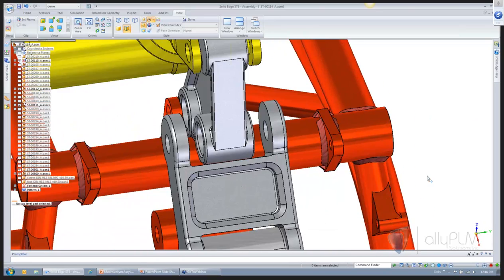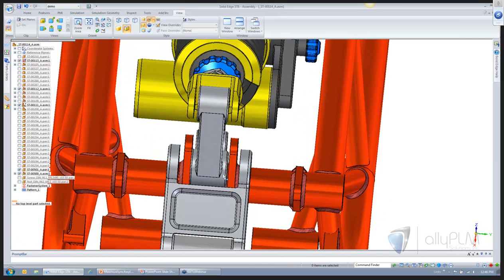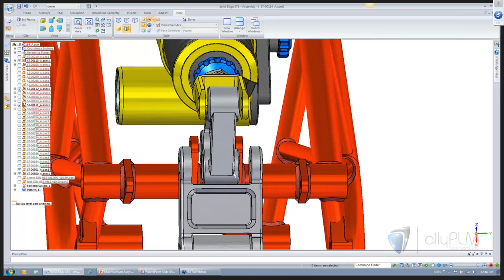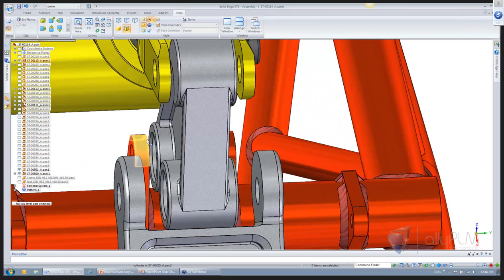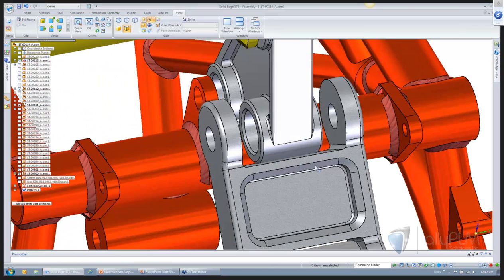Positioning the steering wheel is key to all synchronous edits, both of the part and the assembly. What we have here is a part that had uniform bosses on 3 of its sides. There's a 3 millimeter offset built in between this face and the back face of this here, and we want to honor that same 3 millimeter offset on this boss, but it needs to get larger.